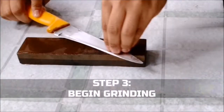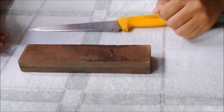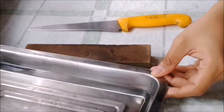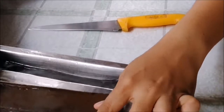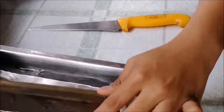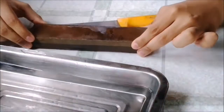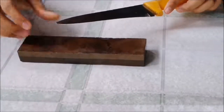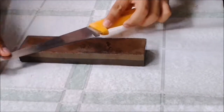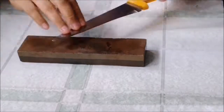Step 3. Begin grinding the blades. Start with a medium grain whetstone. Thoroughly wet the stone by soaking it in water or lightweight motor oil. To maintain the correct angle, press the blade against the concave side of the stone while sharpening. Use numerous strokes, moving the blade in one direction toward the tip as if you are trying to shave off a thin slice from the whetstone. Do not press too hard.